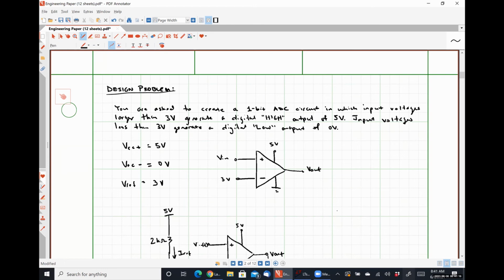So if the really large internal resistance of your voltmeter is in parallel with a small resistance, it really doesn't cause any effect on the voltage that you're measuring at all. But if you're trying to measure the voltage drop over a very, very large resistance, it absolutely will. Similarly, if you're using the ammeter or current meter setting, that is set up to where it has a very, very low resistance, which winds up being placed in series with your element of interest, so that everything flows through the current meter.